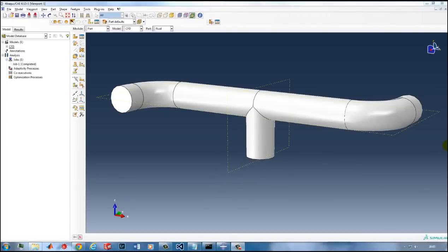The next step is to create the fluid structure interaction. So we want to see the effect of the CFD result on the pipe structure so that we can get the stress contours as well as the velocity contours for the fluid. So the first thing we have to do is copy the CFD model and create a new version which we'll call something like int CFD for interaction.